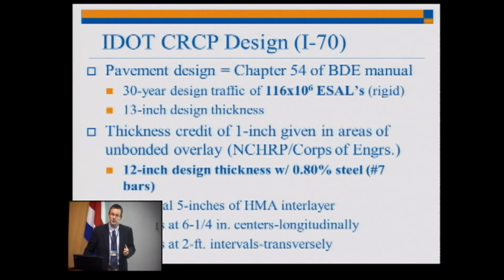And this had over 100 million ESAL design. We put steel in our interstate concrete pavements because it provides more smoothness, and that gives us about a 30-year design life. So that's one of the objectives of our unbonded overlays for interstate traffic.